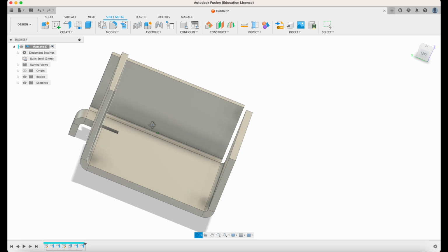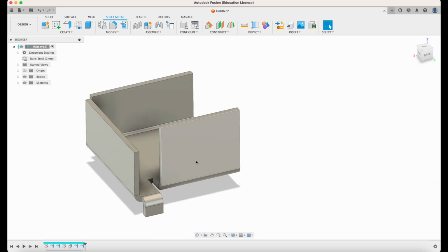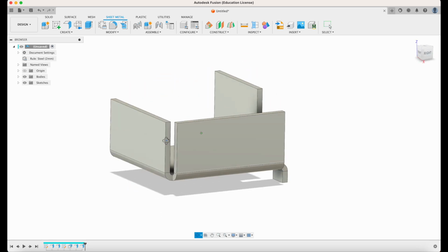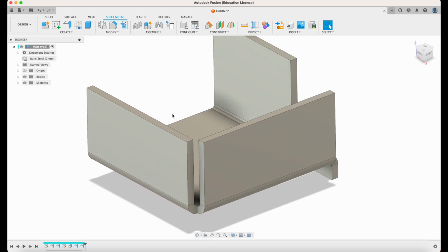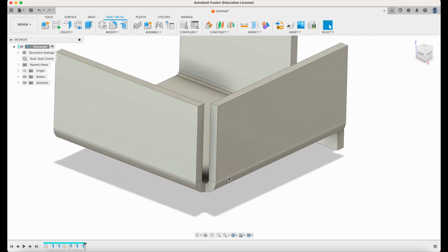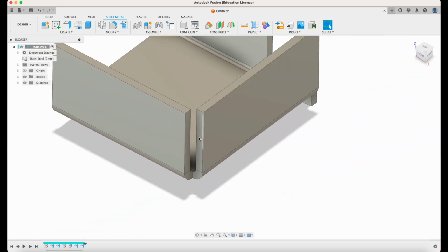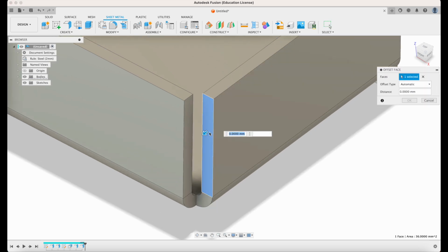So we have this. Now, this is fine for manufacturing. This can be manufactured, but if I were to use this in a product, it wouldn't look that professional because I have these huge gaps. Instead of having those gaps, I can play with this after the fact. And one of the things I can do is extend my edges, okay? Extend my edges as such.